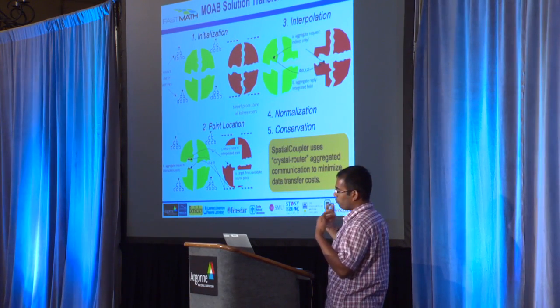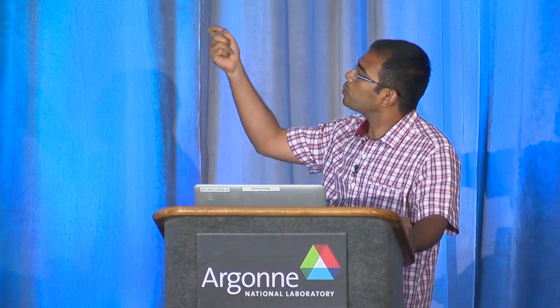So we actually start off with creating a KD tree data structure, which looks at the source points, the vertices in the source mesh, and it builds a tree data structure in parallel, which stores several bounding boxes that store what bounding boxes encompass certain elements in the mesh.